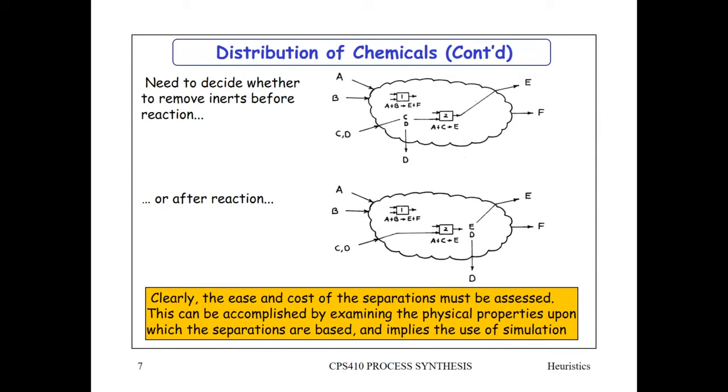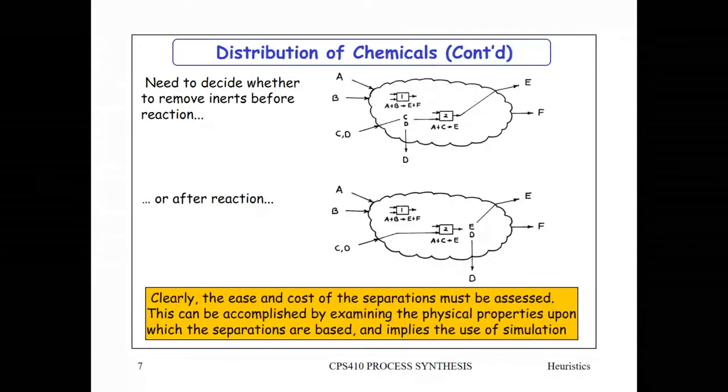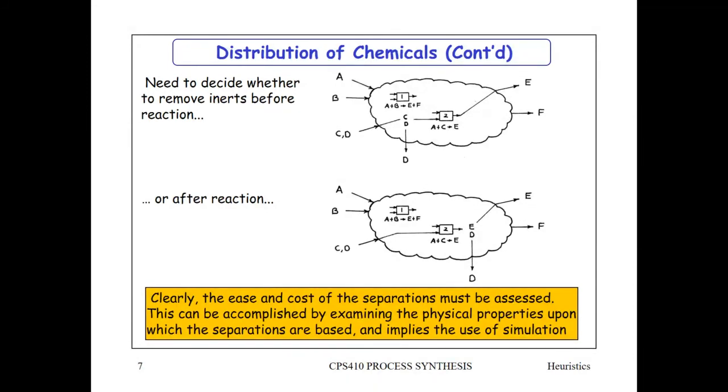What is a large heat of reaction? It is if you use an adiabatic reactor and the temperature goes up, I would say more than 200 degrees, that would be a large heat of reaction, because 200 degrees in a reaction is so large that it needs to be controlled effectively, and that is pretty much why we're talking about large heats of reaction. So look at an adiabatic reactor, see how much the temperature rise will be, and then make your decisions from there on your design.